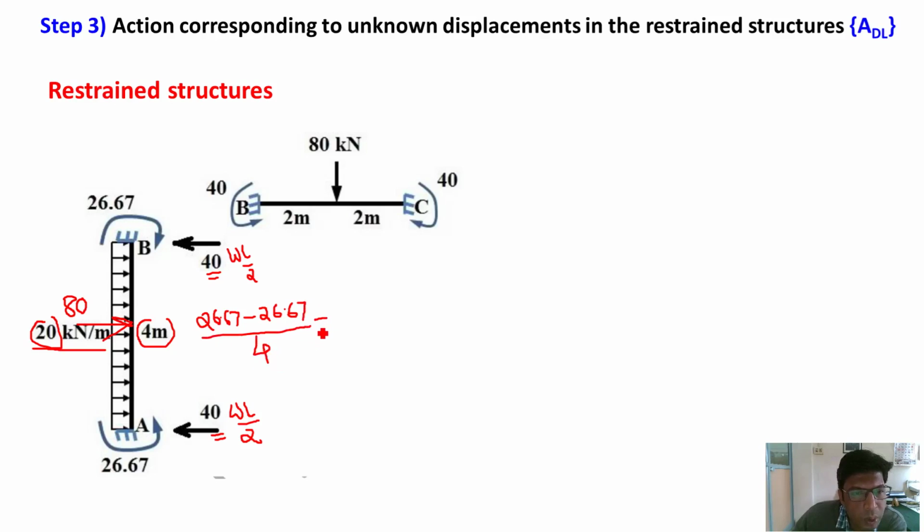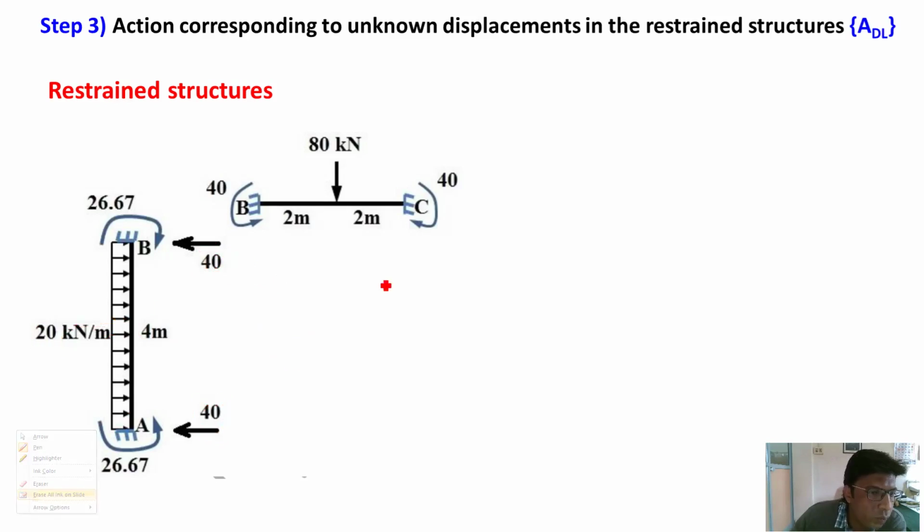So sum of moment, plus and minus, is coming 0. This represents that there is no reaction because of moments. So there is only reaction because of external load, which is 40 at B as well as at A towards left because load is towards right. No need to find out reactions of beam.